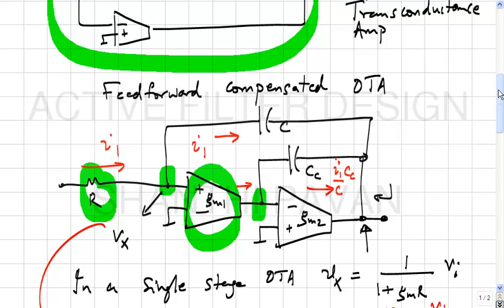That is basically what is physically happening, correct. Now, if the fellow who is supposed to do the whacking himself is very slow and relaxed, then obviously there will be a lot of error at the virtual ground node because the forward amplifier is not doing its job fast enough, all right.